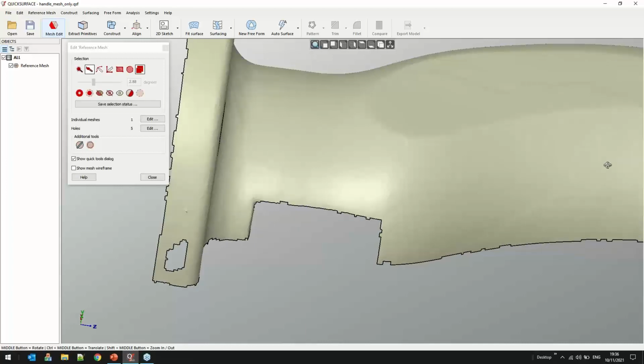How I can do this, I will just delete this with the normal selection tools, and I'll try to close this. Now I go to edit the holes, and what we have now is the fill semi-holes. How it works, you select one point of the semi-hole, select the other one, and now the software doesn't know what to fill in, so you need to make a third click and select this to be filled. In this way, you can actually fill all the semi-holes.